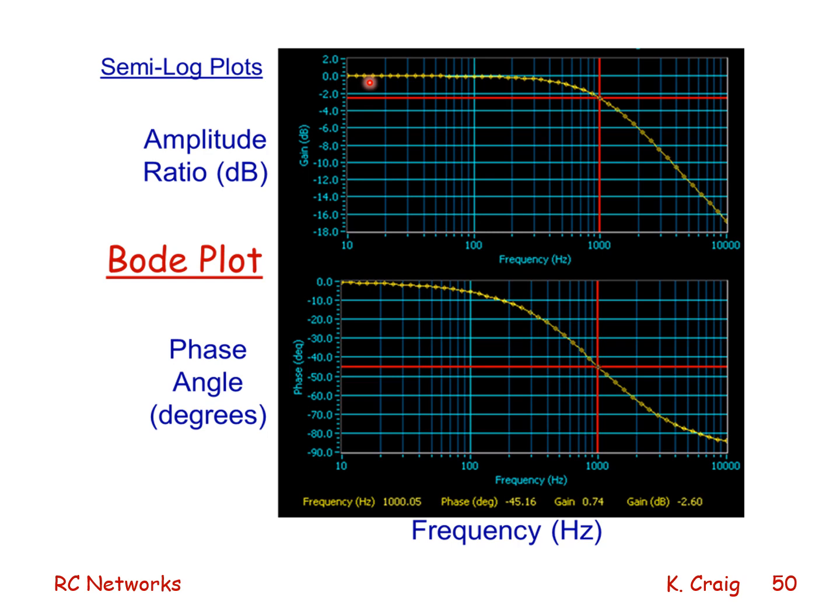Compare the two sine waves, determine the phase angle, and plot it. And do this for each frequency represented by the dots on this curve. So this might take an hour to do. With the MyDAC Bode plotter, which is a virtual instrument which you will be using in the National Instruments device MyDAC, this is done automatically in a matter of seconds.